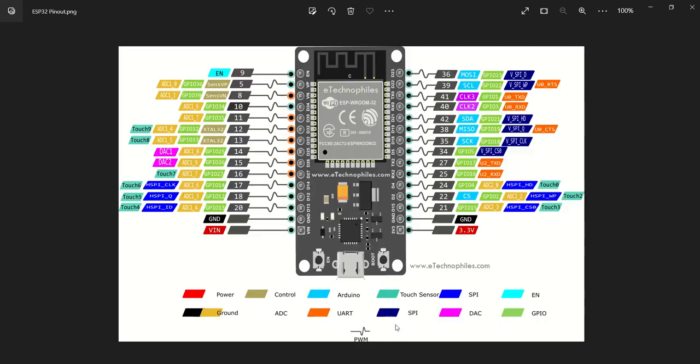The controller that I'm using is an ESP32. This is compatible with Arduino, but the great thing about these ESP32s is that they're extremely cheap. We get general purpose I/O, analog, digital, all that good stuff. We've got our SPI communications, I2C communication, but we also have Wi-Fi and Bluetooth enabled chips. That allows us to do wireless communication, which brings us into this IoT sphere without any need for additional hardware or modules. In some Arduinos you have Wi-Fi built in as well, but some you don't, and you have to get additional components. So at least this is all built in.